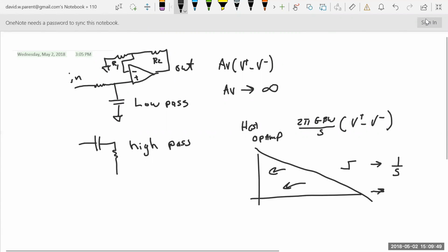You always start simple, then go more complicated. And that's the gain bandwidth, and that would be 0 dB. Now, if you've designed a filter, you do a step function, and something isn't working, like ringing, then you start using these more complicated models to get to the bottom of it. All right.